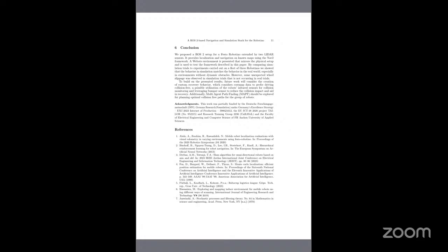For localization, they used the Nav2 framework in ROS2. Localization means identifying the location of the robot. To do the localization, they used LiDAR, EKF, and AMCL. They developed a navigation system to move from one location to another, using a Theta* planner and an MPPI controller.